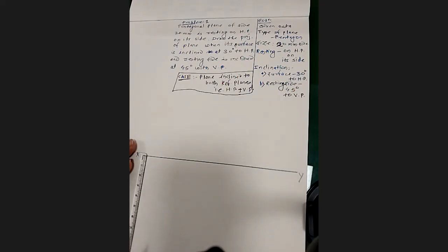From the XY line, you can take any distance, but make sure that it should not touch the XY line. So right now I am taking 20 millimeters. I will add the comment afterwards. First of all, get this 20 millimeter line.